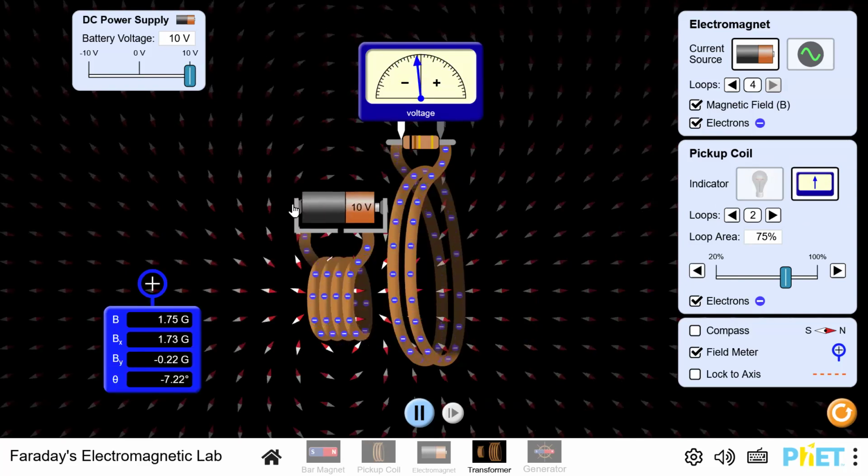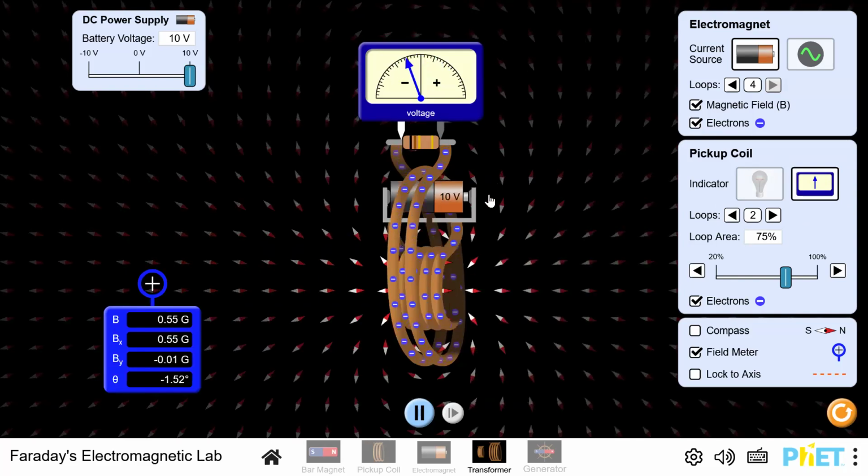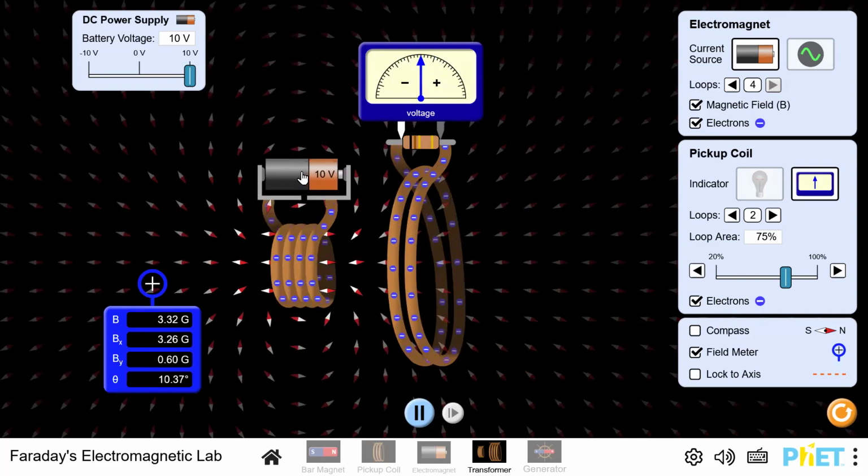It doesn't really show the voltage. But anyway, if you have a primary, the one that's actually attached to the power source, and it has 100 turns of wire, and you have a coil that's not attached to it that has 10 turns of wire, you're going to have a 10-to-1 ratio. It's going to drop down. So from 100 volts, it'll drop down to 10 volts.